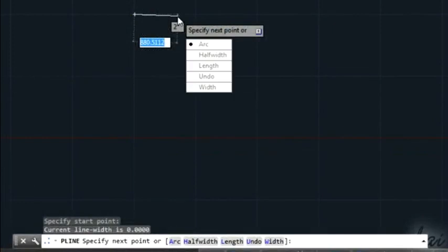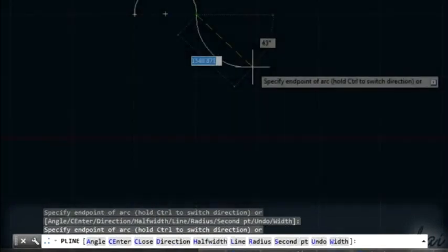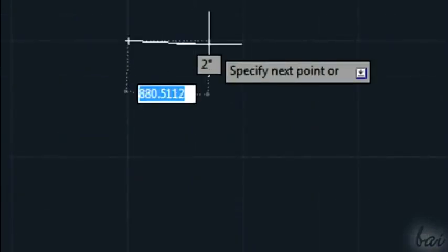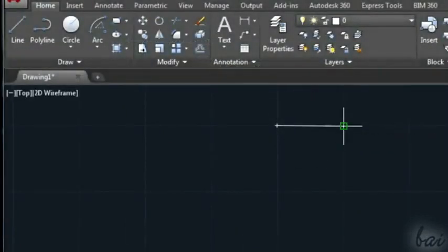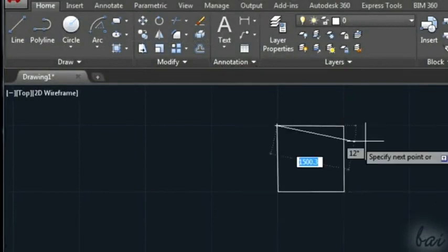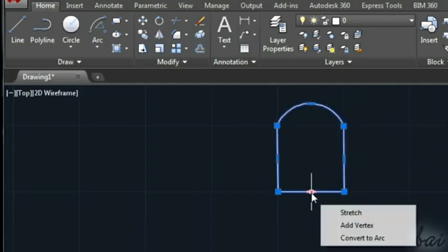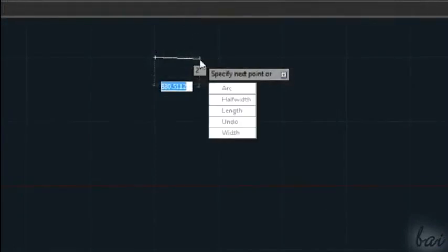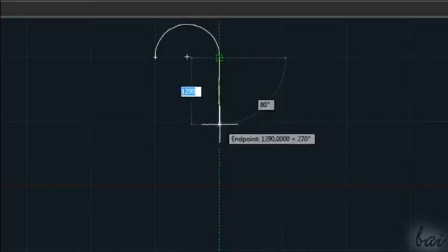Whenever you draw or edit objects, the command line helps you at being precise. This is located at the bottom of your workspace and also appears close to your pointer while you work, with a list of sub-options. For example, if you draw a polyline, the dialog box lets you change how to draw it. You can draw it first as a polygon and then edit it to give curves. Otherwise, you can use the dialog box to insert curves from the start while you draw.